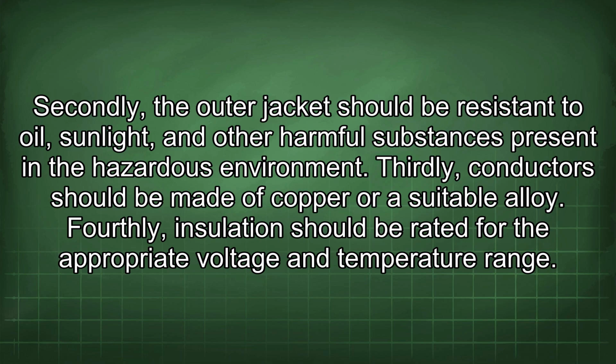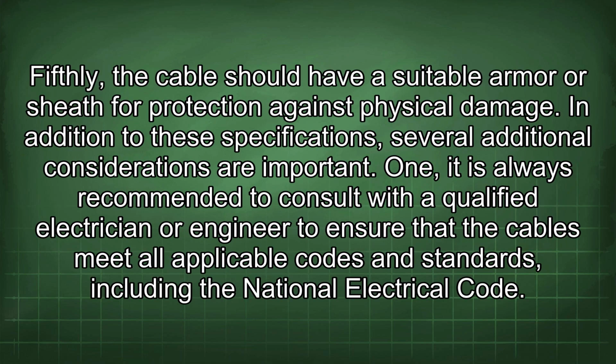Thirdly, conductors should be made of copper or a suitable alloy. Fourthly, insulation should be rated for the appropriate voltage and temperature range. Fifthly, the cable should have a suitable armor or sheath for protection against physical damage. In addition to these specifications, several additional considerations are important.